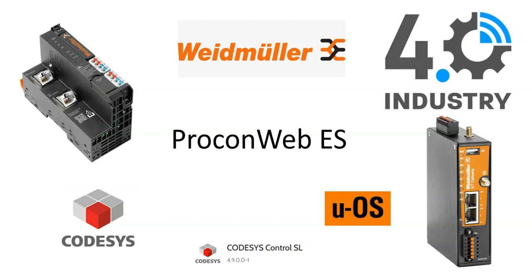Just to explain what we actually mean by ProCon-Web ES, or embedded system, it literally means the ProCon-Web visualization or HMI application lives on board the Weidmuller hardware, whether it be a controller or an IoT gateway. Unlike the conventional HMIs where you have a proprietary piece of hardware and proprietary software, the HMI visualization is just broadcast via a browser, so there is a browser or web server integrated into the controller and the gateway. So embedded system literally means the HMI project lives in the controller.